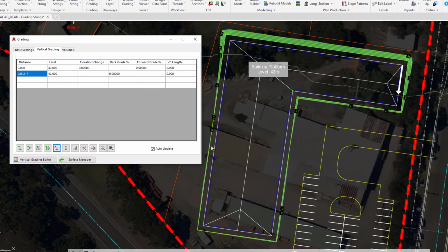There may be an occasion where you have multiple different points along your polyline, and running the add IP by selection in the drawing is a fairly manual process. However, there is an alternative way of doing this, which is to add an IP at every change of geometry within or along the polyline. So we're going to go ahead and click on this particular button now.